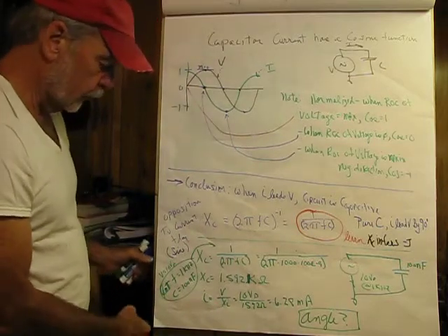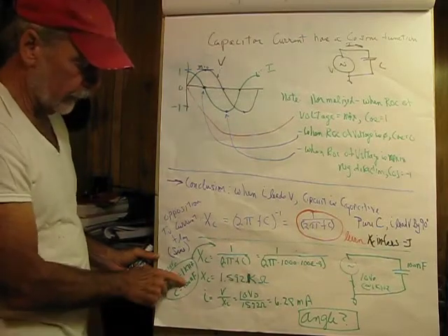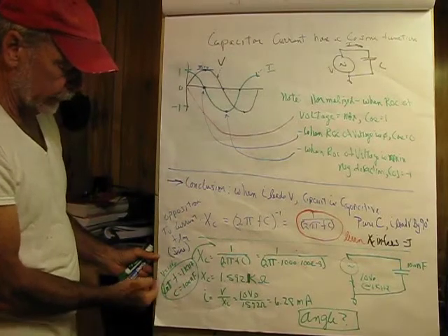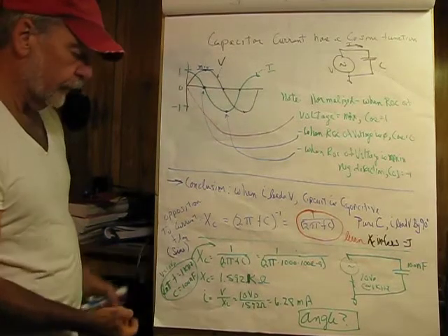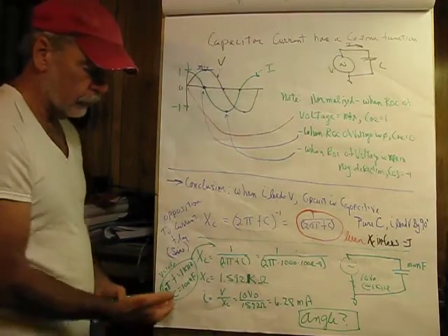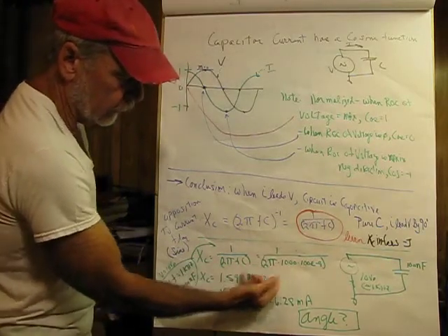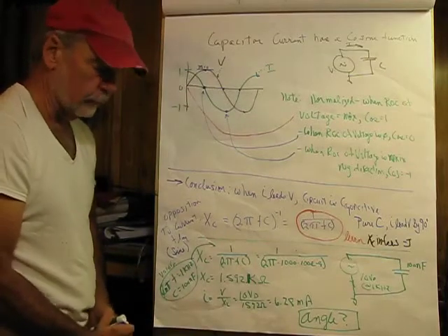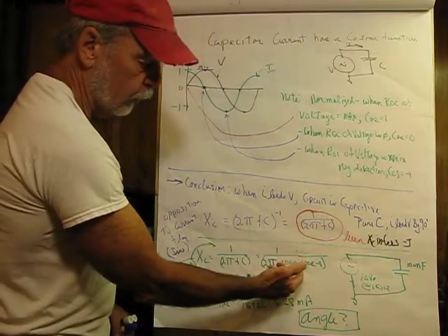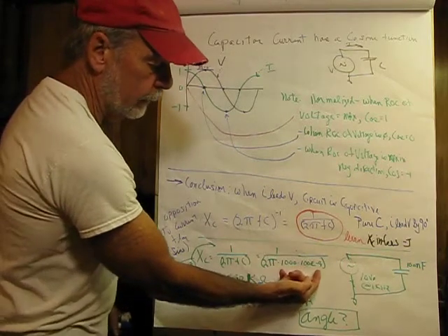So for example, if we take a simple circuit here, and we'll let C be 100 nanofarads, that would be 10 raised to the -9th. We'll let the frequency be 1K, and the voltage in the circuit here be 10 volts peak. First order of business is to determine the capacitive reactance. So that would be 1 divided by 2 pi Fc, and there you see I've elected to write the 1 kilohertz as 1000 because I can hit the 0 buttons pretty quick. And for the value of the 100 nanofarad capacitor, it's 100 e to the -9th.